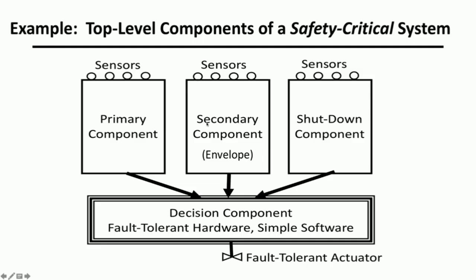So, of course, the same happens to this one, and the same happens to this one, and the same happens to this one. So we do have here complex software, and I phrase it, complex software on unreliable hardware. So we cannot trust it. And as I said, if we are very careful in designing, in testing and so on, we might come up to the 10 to the minus 4, 10 to the minus 5 failure rate per hour, but definitely far from the 10 to the minus 9, which we would like to have in a safety critical system.